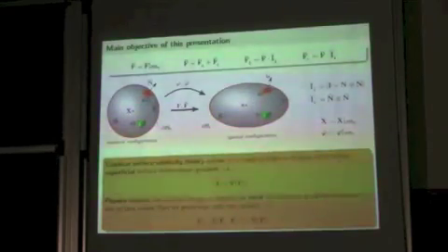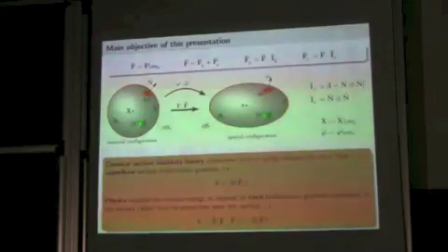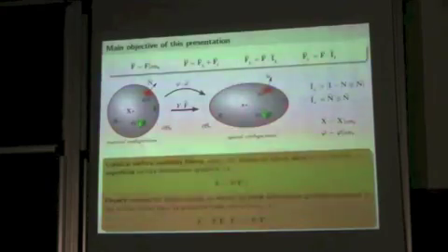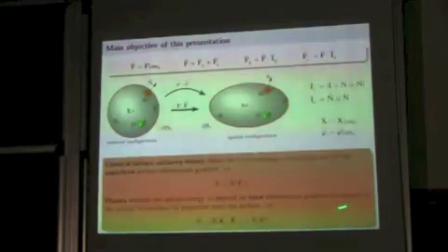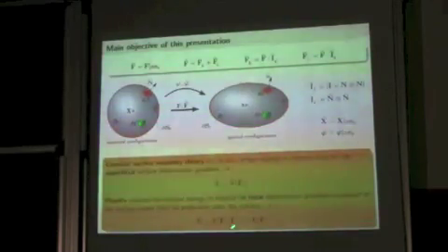So this is sort of Gurtin's assumption from starting with the surface elasticity theory. And the simulations I showed you already use this assumption. Okay? So the energy depends only on this tangential part. But physics requires the surface energy to depend on total deformation gradients evaluated at the surface rather than its projection